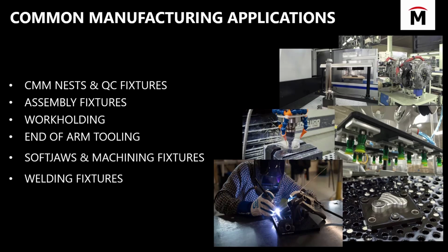Soft jaws, typically required for subtractive manufacturing. So we're talking about soft jaws for like your Kurt vises. These things are typically time consuming to machine, so you really should be giving 3D printing these things a go. We're seeing lots of customers having fantastic success. Next, hold down fixtures for secondary operations. That's a really good one.